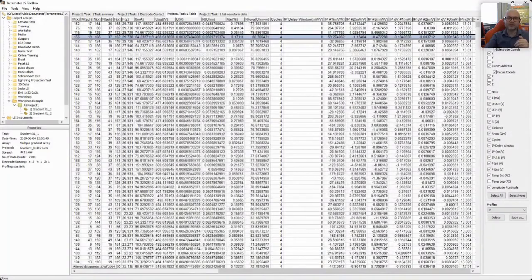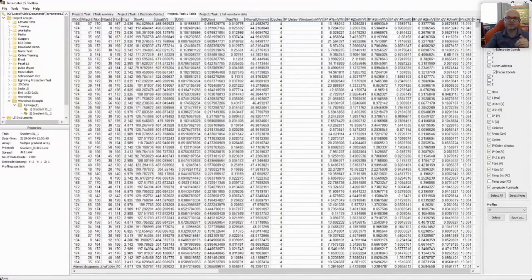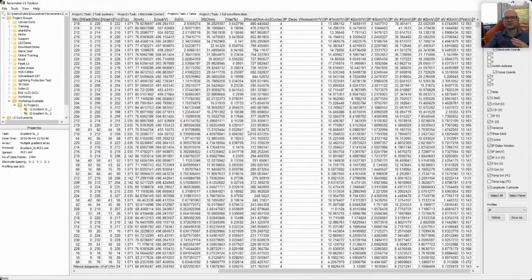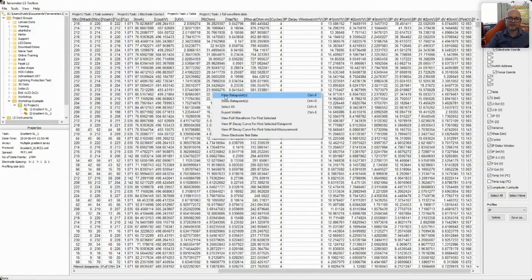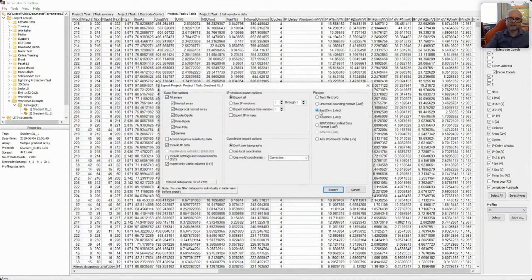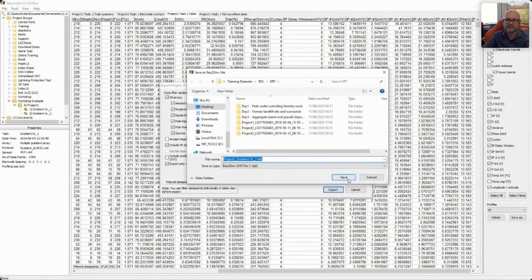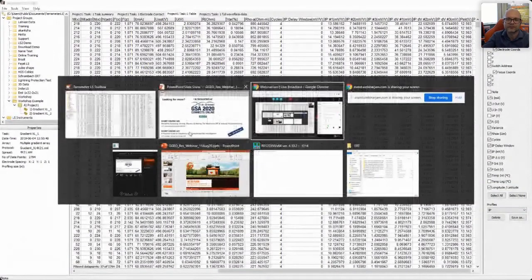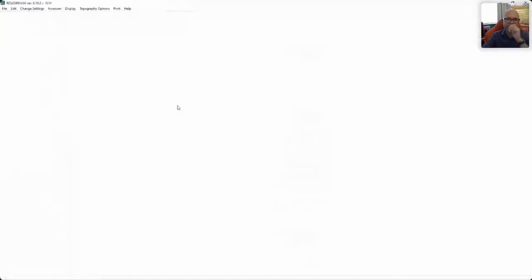I can have a quick look at the apparent resistivity, so make it small to large, make sure there are no obvious statistical outliers, then make it large to small, and it varies pretty smoothly. So I don't really need to filter anything else out, so I just right click and export. I'm going to export it to the Res2D format, as a flat data set, but I could apply topographic correction if I wanted. Save that. And then I'm going to switch to Res2D and look at what additional functions we have in there before I wrap it up for today.